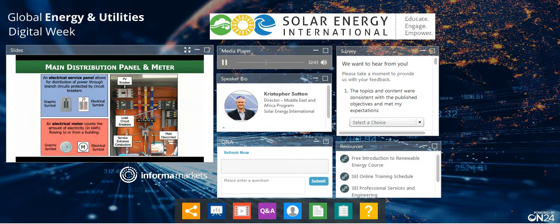So just thinking about where energy flows through the system, it can either run from the PV to the loads, or if there's more solar than the loads, we can push right through and out through the service entrance conductors back out to the utility grid.